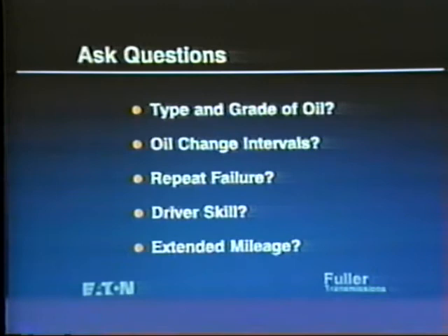Look for answers to questions such as, has the proper type of oil been used and has it been changed regularly? Is this a repeat failure which wasn't analyzed correctly the first time? Is there a history of driver-related problems? Or has this unit lived out its expected life?